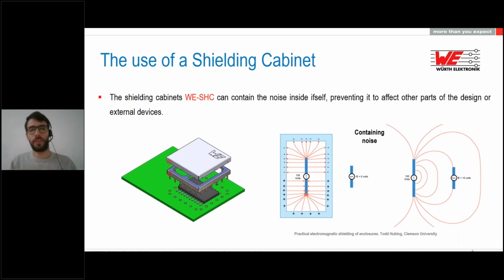For example, RF is a very sensitive design, and we always need to keep the impedance steady and the same. What's happening is that we have some coupling that could be coming from common noise, for example. This coupling can increase the impedance of the lines in the RF stages. And then the matching that we designed for our antenna is totally messed up, and the radiation pattern that we calculated for our antenna is not working anymore.